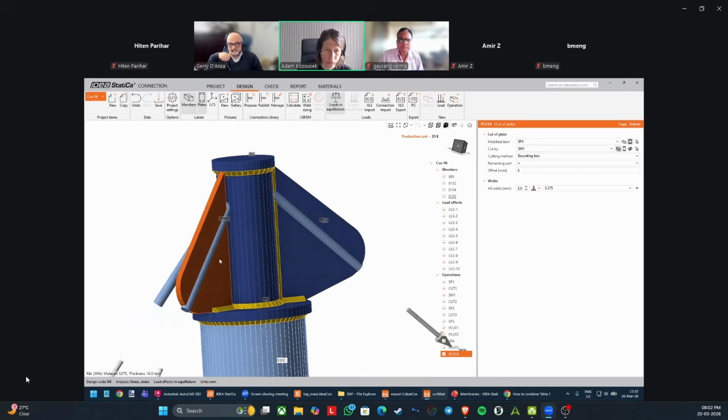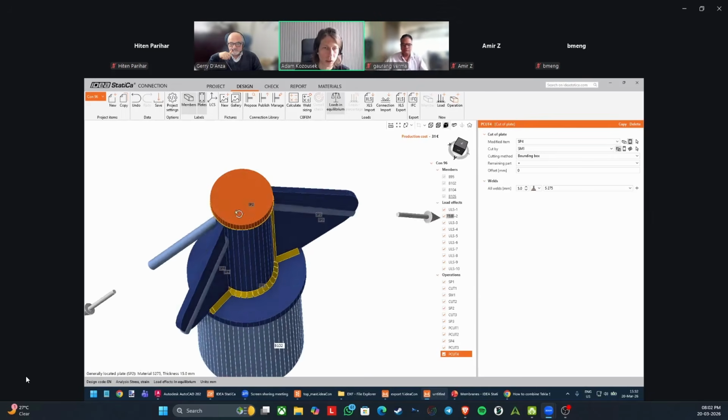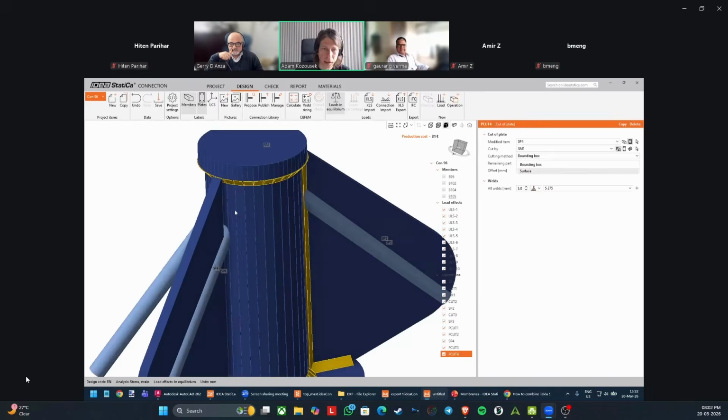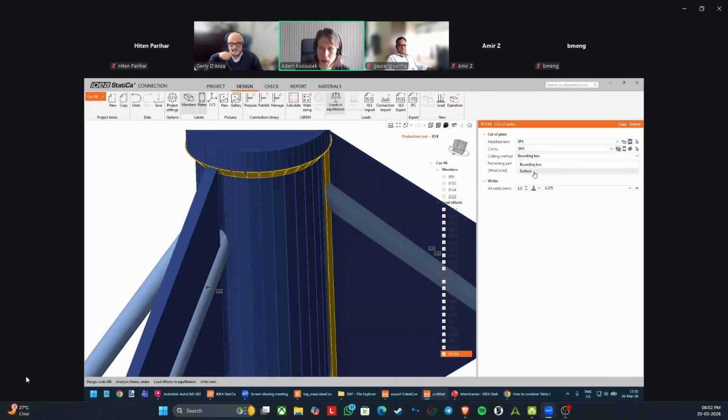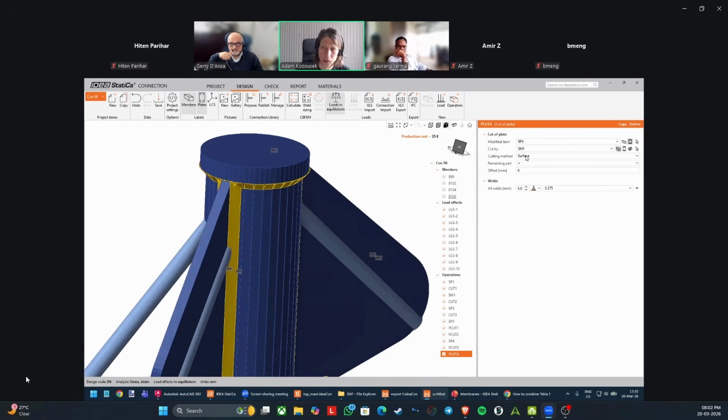Okay. So there are two cutting methods. It's either bounding box or surface. Bounding box is a virtual box that surrounds the member or the plate of the cross section. So the bounding box of this tube is basically some virtual polygon around it. And the surface is basically the surface that you see.